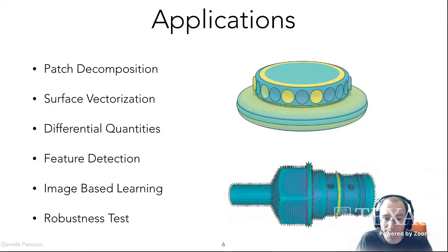Just to give you an example, even computing normals, just by computing normals on faces and then averaging them on vertices, is something that you cannot do on this large collection, or at least if you implement it in a naive way, you're going to get for some models some nonsense, just because you have unhappy floating point cancellations. And at this scale, this small possibility of failures actually will lead to trouble.